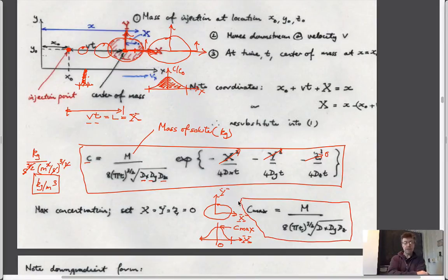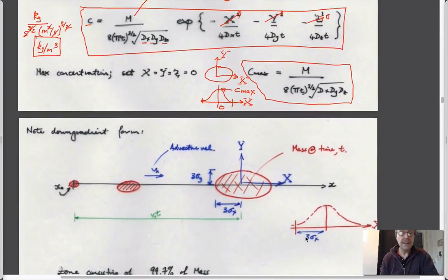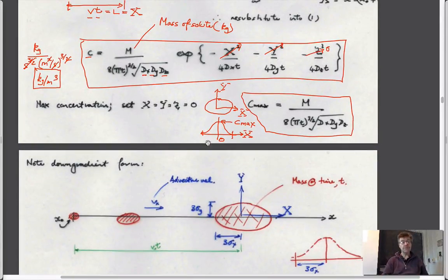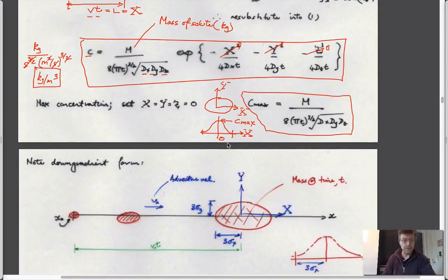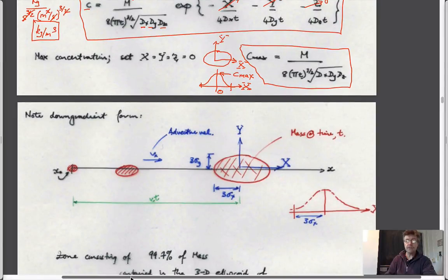It doesn't matter so much about understanding where the equations come from, but getting a feel for what they physically mean, I think, makes some sense. And so you could always get the maximum concentration as it transits downstream just from this expression. Kilograms, seconds, meters squared per second, and so on. And so a standard result that comes out of that, because really, if you think about it, this distribution that we have here is nothing other than the normal probability distribution, the so-called Gaussian distribution that we curve things on typically.